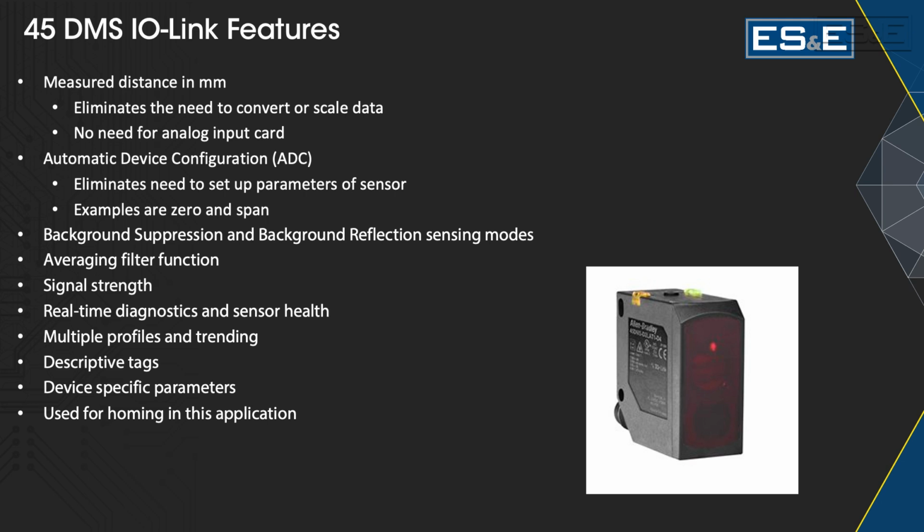So what about a distance measurement sensor? You know, if we use one of these, you can know exactly where the plate's at on the conveyor at all times. Right. We'll probably know that for the servo, but maybe we could use this as a homing, a home position, maybe. I think that'd be a great idea.